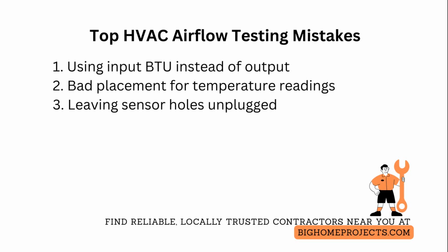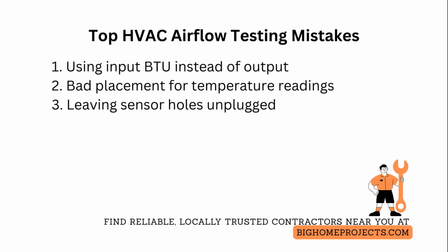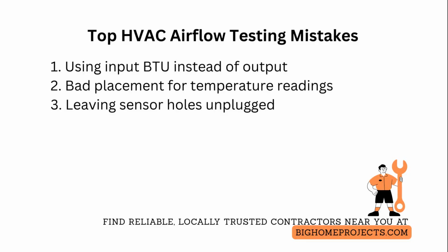Another common error in airflow diagnostics is taking supply and return temperatures too close to heat sources or leaks, causing false high or low temperature rise. Fix it by drilling test ports on straight duct runs at least 10 duct diameters from transitions and averaging multiple insertion points.